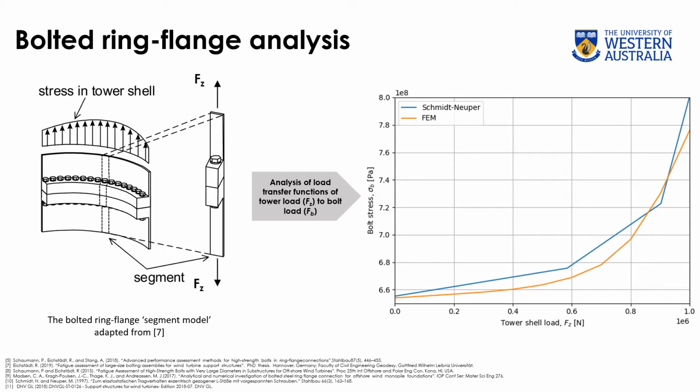This method is efficient, however does not treat bolt bending, does not model stress hotspots, and only bounds flange imperfection tolerances. ST0126 also permits the use of structural finite element simulations to simulate load transfer. FEM simulations are likely more accurate than the analytical method, however will be much more computationally expensive.